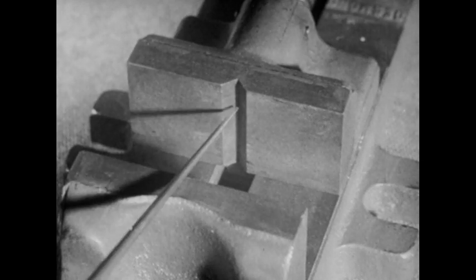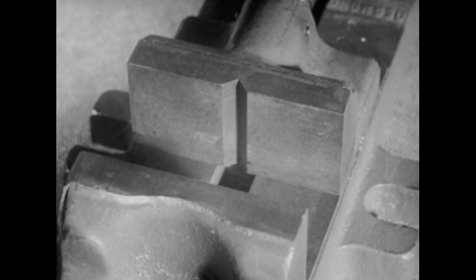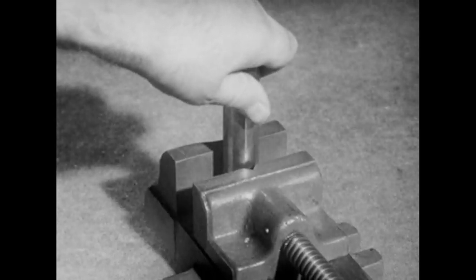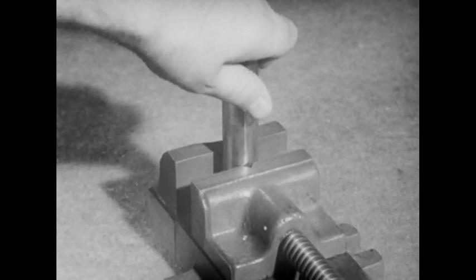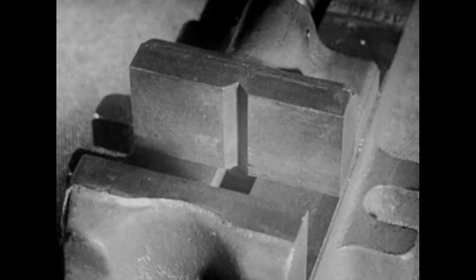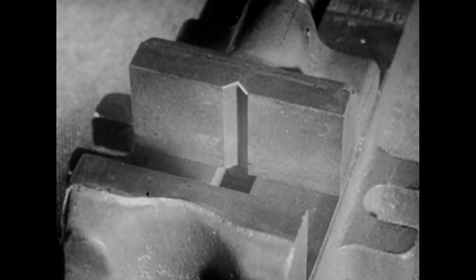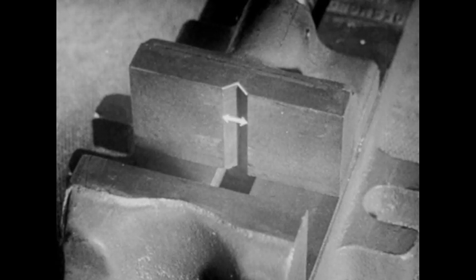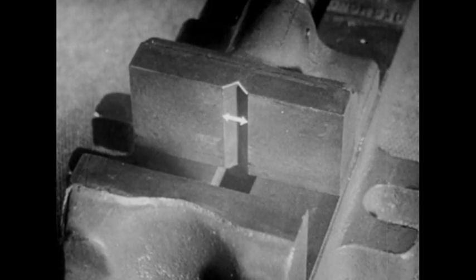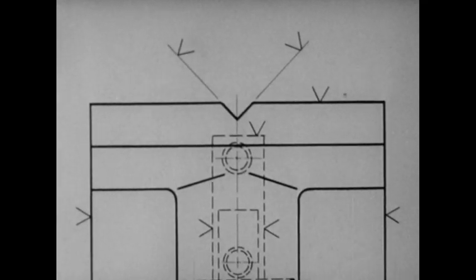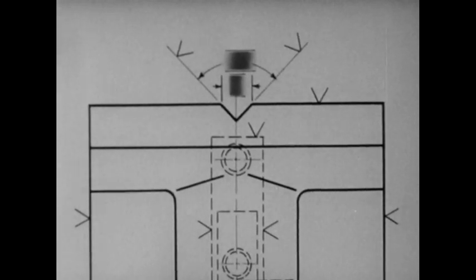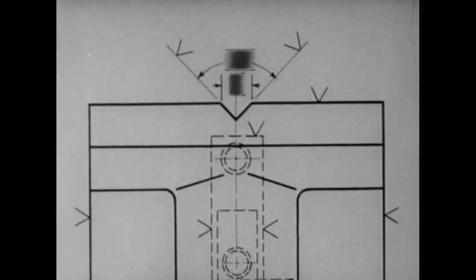The V cut in the movable jaw is used to hold cylindrical pieces in a vertical position. The sides of the V will keep the cylinder from slipping laterally. Give the included angle and the width because they are most convenient for the workman to use in making the cut. Show these dimensions on the top view where the shape of the V appears and the dimensions are easiest to read.